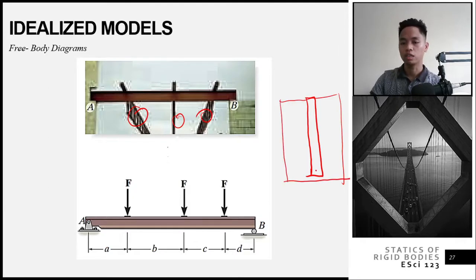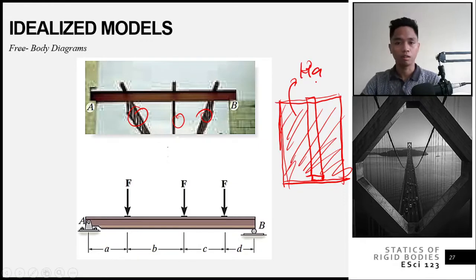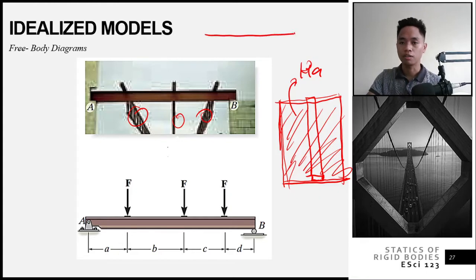You will encounter that soon. If this is your girder and this is your slab, your girder carries the load within its tributary area. And that load is in kilopascal, as I discussed in the previous video. Since it is in kilopascal, to make it easier to analyze as a girder, our girder here is already shown.